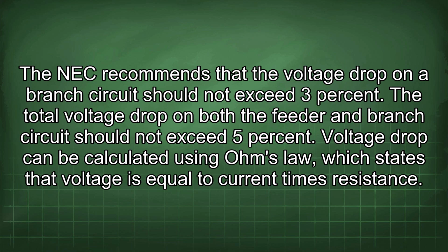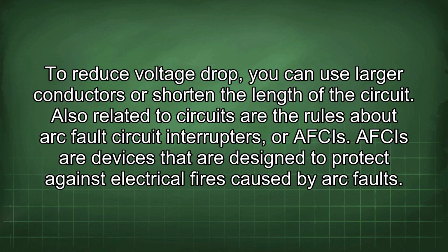Voltage drop can be calculated using Ohm's law, which states that voltage is equal to current times resistance. To reduce voltage drop, you can use larger conductors or shorten the length of the circuit.